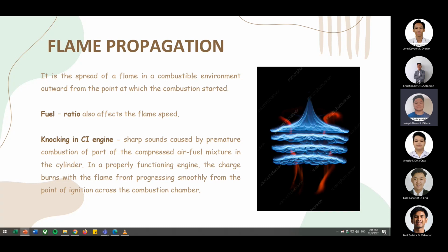Closer to the TDC, if additional fuel is permitted to be pumped into the combustion chamber before it begins to burn, there is a sudden rise in pressure that results in jamming pressure against the piston and rough engine running. The rate of pressure increase will rise quickly if a longer ignition delay is permitted, leading to high pressure differentials and intense gas vibration that can cause audible knock.